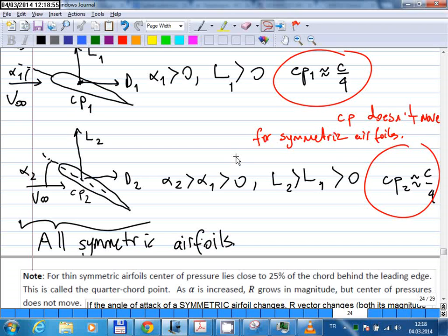That's true. Well, that condition is called stall condition, because the angle where the lift force reaches a maximum is called the stall condition, and if you increase the angle further, the lift force will start going down. Well, I will be talking more about that, the stall phenomena. Obviously, it depends on a lot of different factors. It depends on the airfoil shape, obviously, but it depends on other things as well.